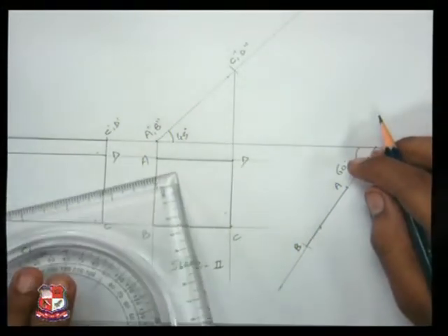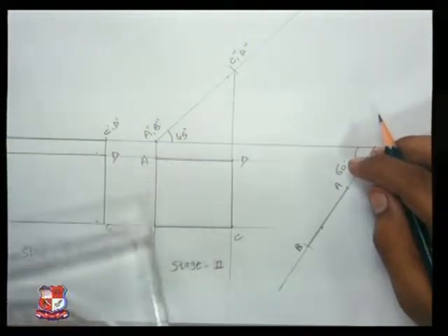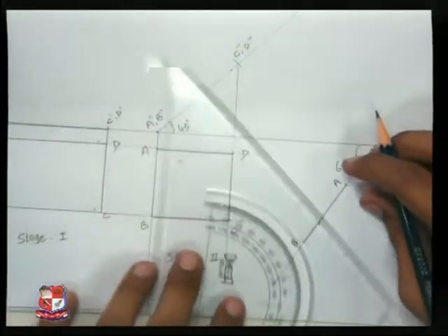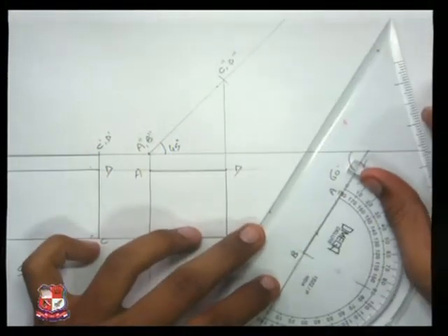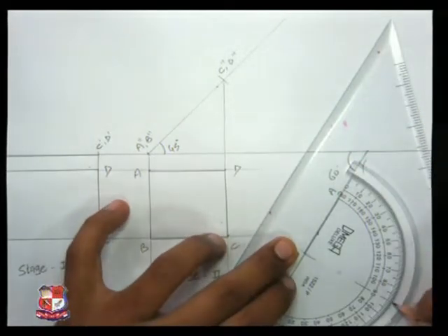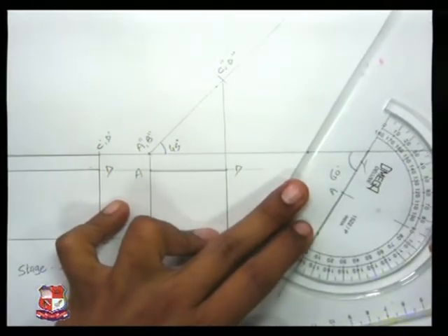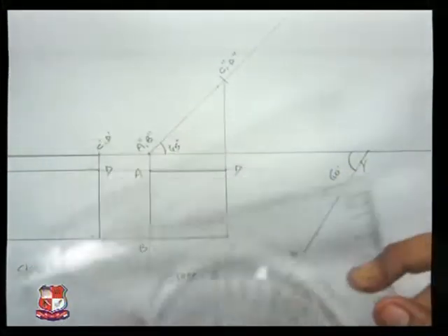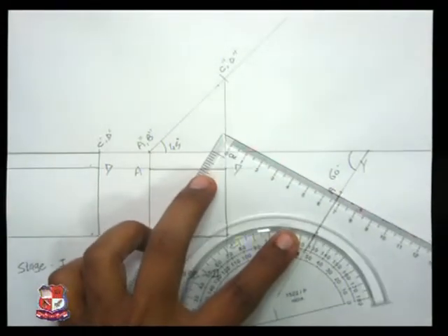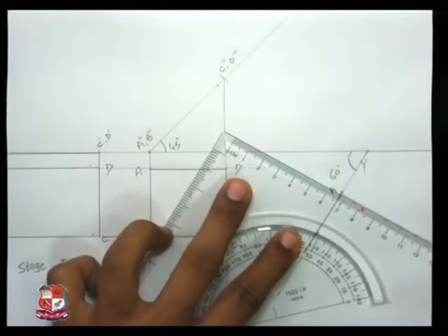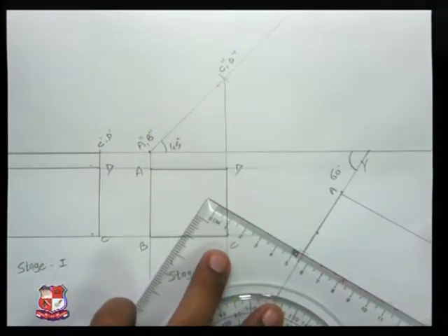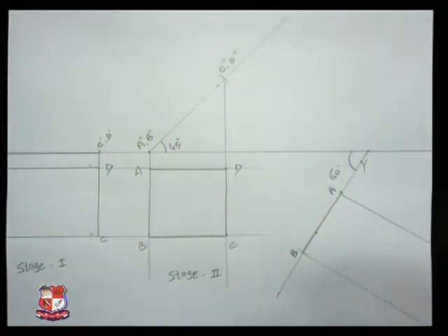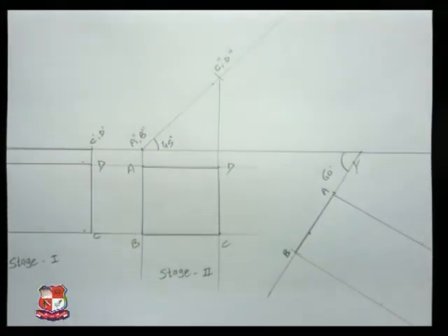As you can see that AB and CD are perpendicular and BC is also perpendicular. So we will take out perpendicular lines from A and B and draw the reference line from it. Take out perpendicular reference line from A and B both. Draw very light line initially. I've drawn the reference line as well.